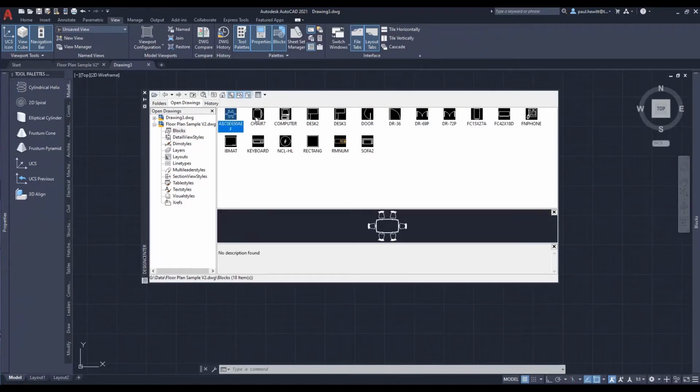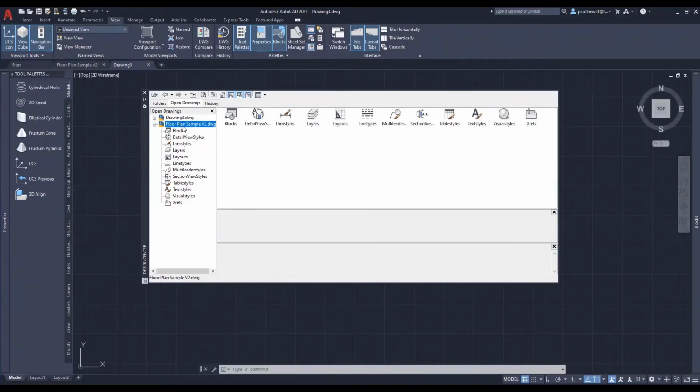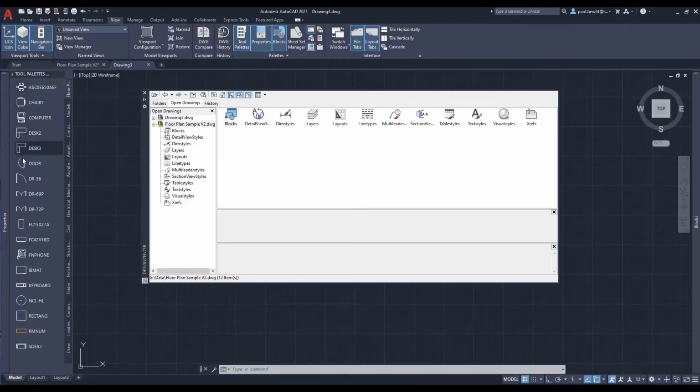Just navigate to the drawings, or more convenient, any open drawing, and drill down to the content you need. Often using Design Center can be more efficient than recreating content or reattaching XREFs. In addition, there's no easier way to create a tool palette from the drawing that contains your block library. Simply right-click in the content pane and select Create Tool Palette.